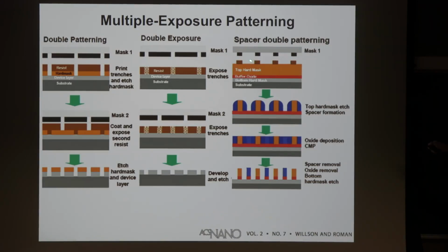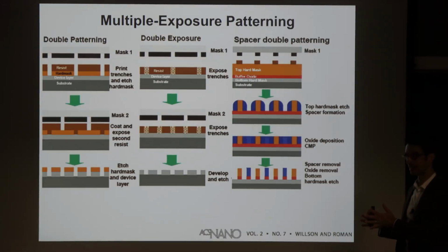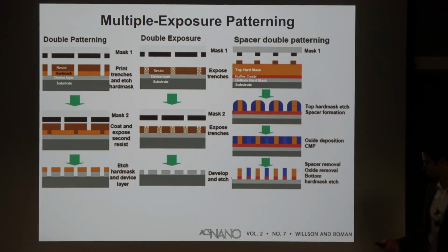So now you had something that had a very low resolution, and now you have all these little features in here that you can do whatever you want with just by using the sidewalls as actually containing information. Now, if you use the right kind of etch chemistry, you can get something with a much greater resolution than the mask you originally started out with. So all of these techniques combined with immersion optics and phase shifting masks are the techniques that you use to cheat the system. They're the techniques that you use to get high resolution features from very long wavelength light.